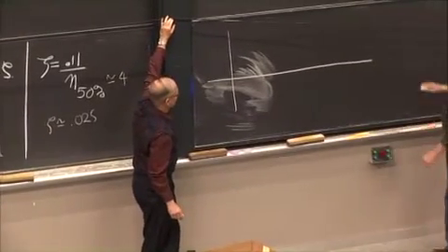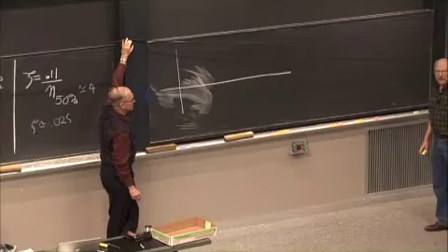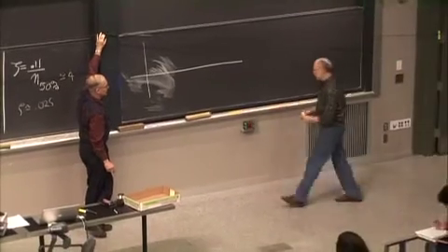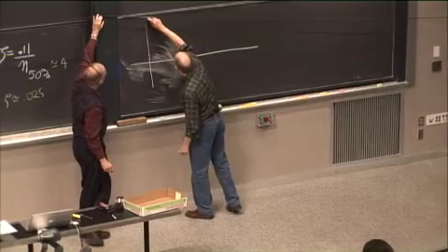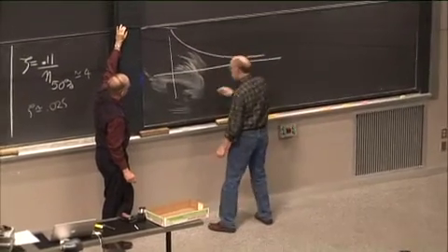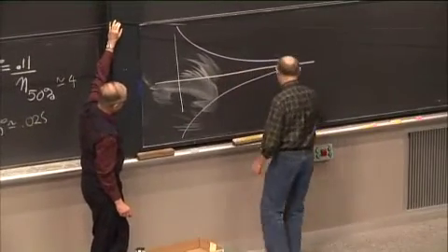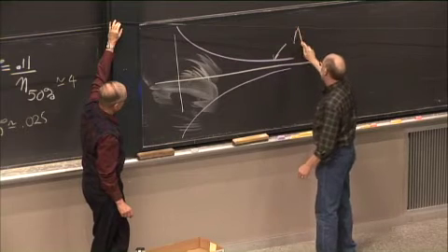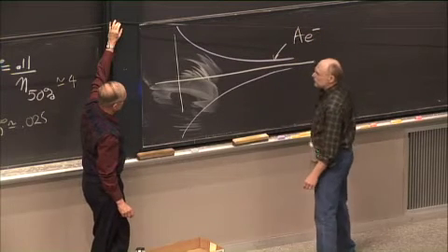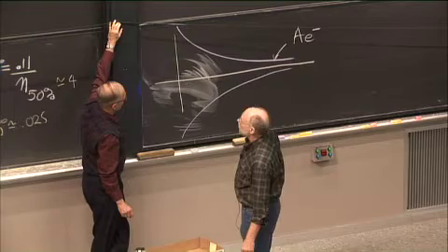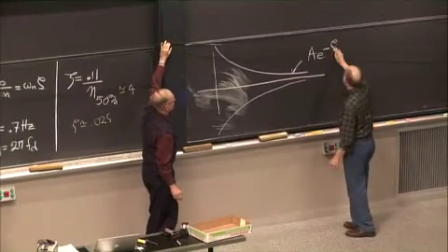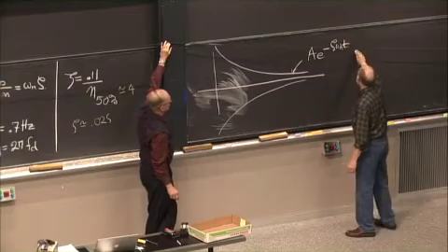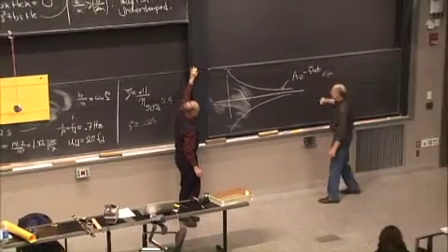So the first thing I want to do is graph this damped response that we have here. To do that, I'm going to first draw the exponential part. This is the exponential decay and the negative of that. So that's the curve A e to the minus, what was my equation here? Zeta omega n. Thank you. Zeta omega n t, and that's the exponential decay.